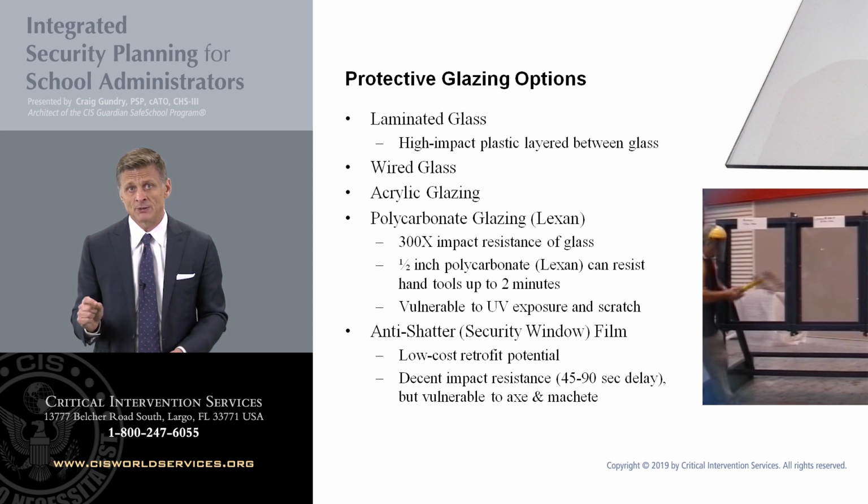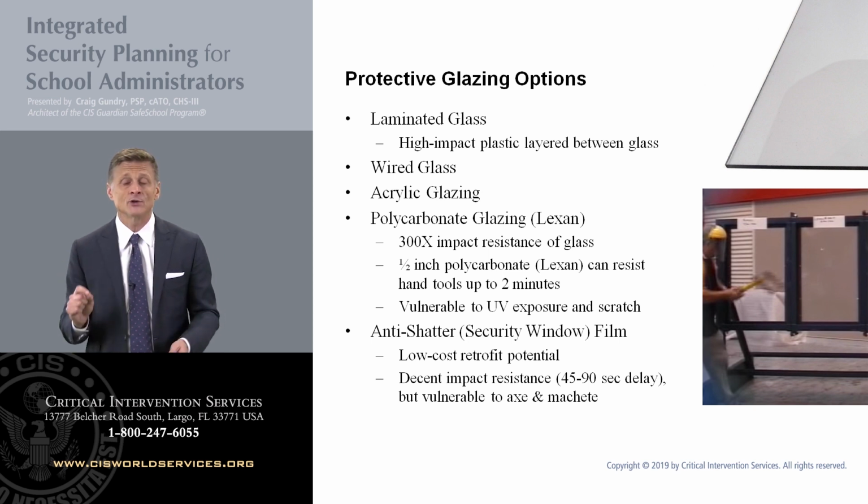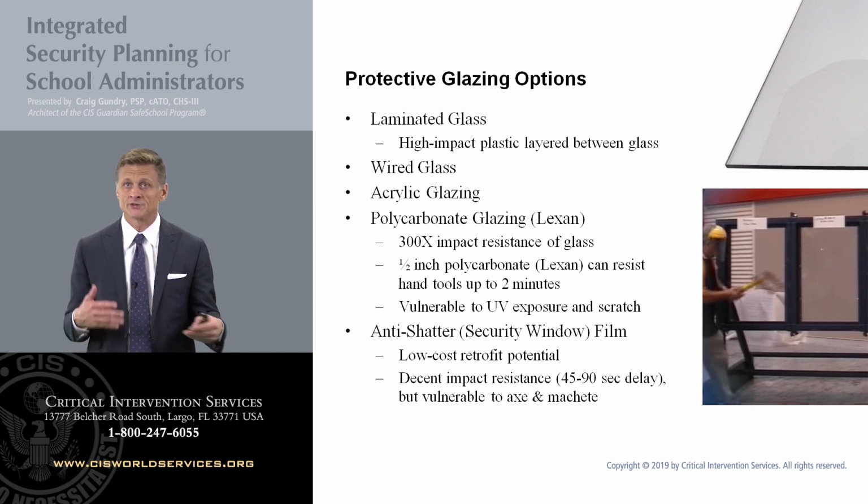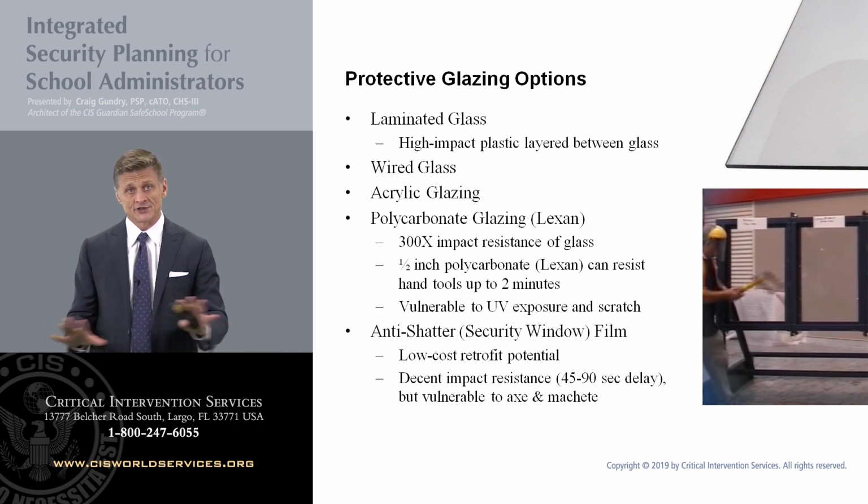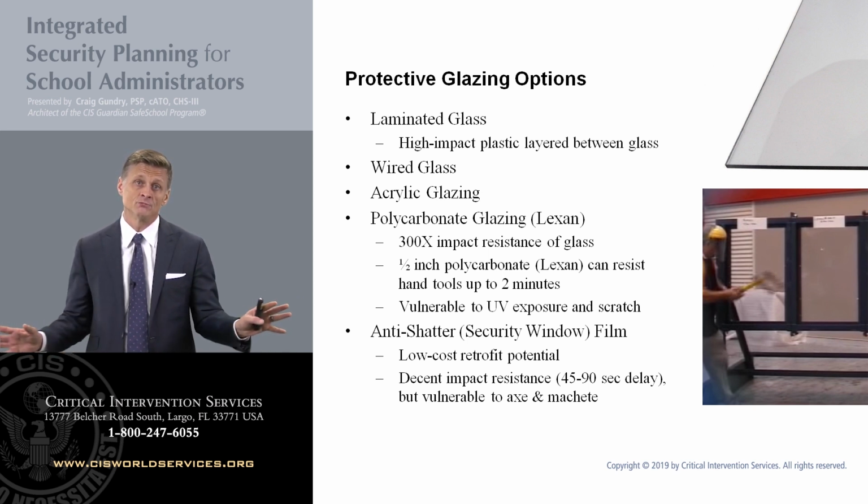Another disadvantage of polycarbonate is it is not very resistant to scratching. So if we're installing polycarbonate in areas where we have a high volume maybe of students passing with book bags that could be brushing against it, probably within a period of time, maybe 6 months to a year or two, it's going to start getting a lot of scratches and will look unattractive.